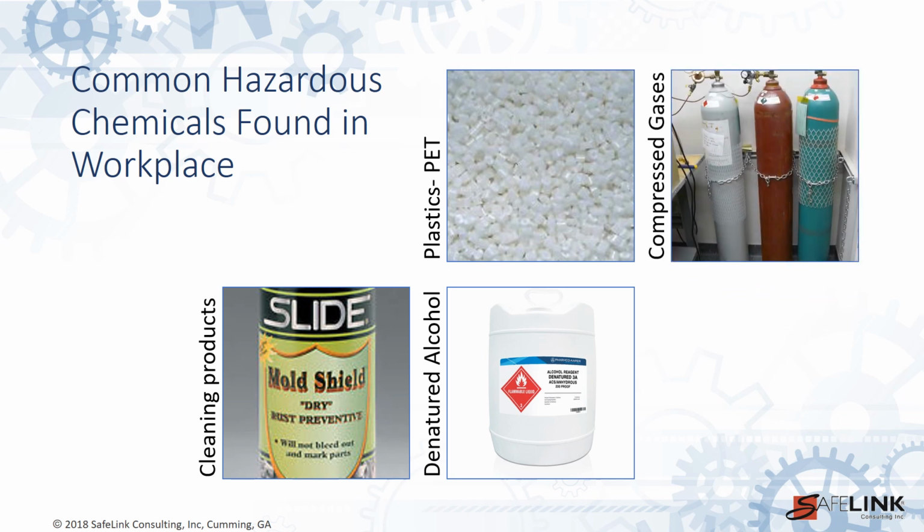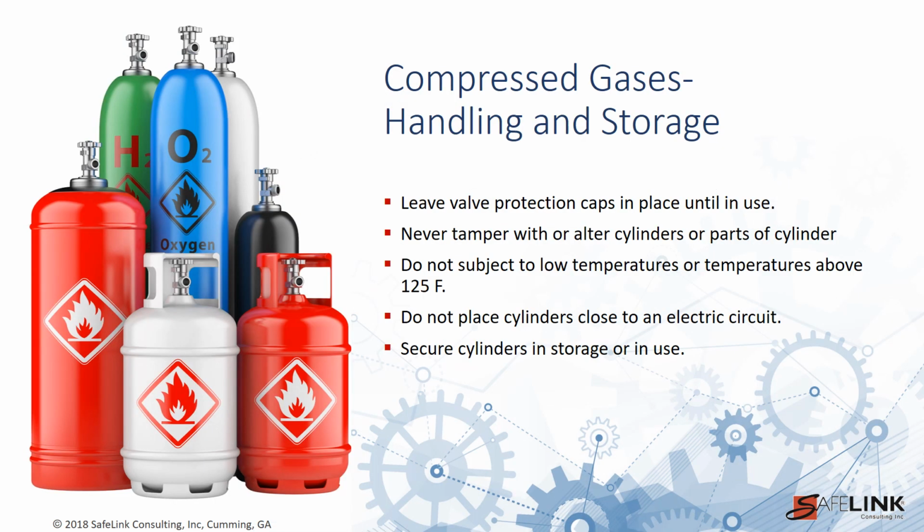Note that compressed gas cylinders are considered a chemical. Let's review some safe practices necessary to protect workers who are handling and storing compressed gas cylinders. Leave valve protection caps in place until cylinders are secured and connected for use. Never tamper with or alter cylinders, valves, or safety relief devices.